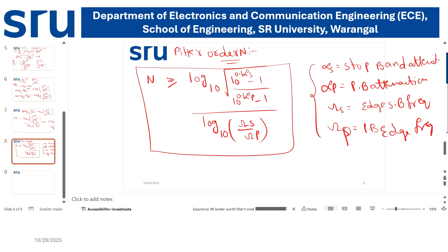Now, we have two different formulas for finding the order of the filter in terms of stop band attenuation, pass band attenuation, stop band edge frequency and pass band edge frequency. Suppose I consider epsilon is equal to square root of 10 power 0.1 alpha p minus 1 and lambda is equal to square root of 10 power 0.1 alpha s minus 1.